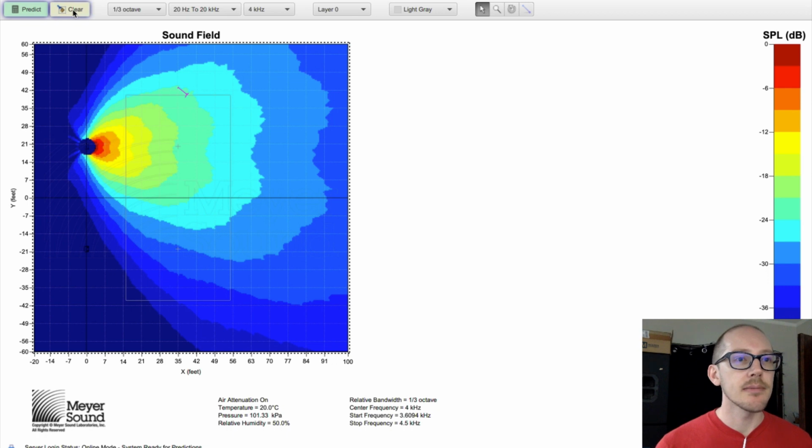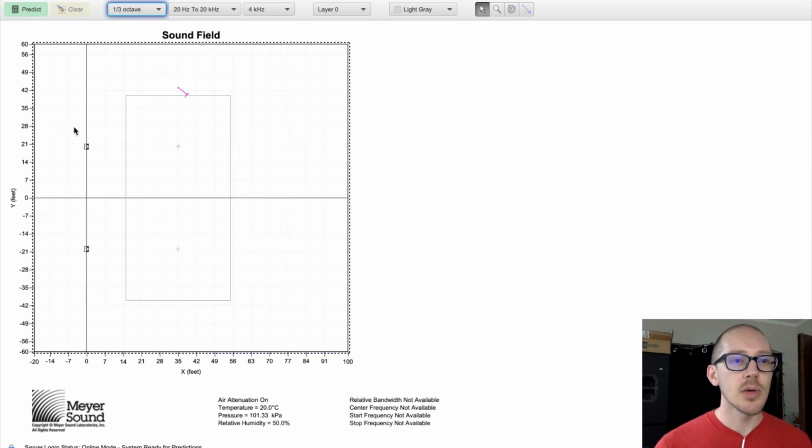But pretty good. Okay, so now in terms of placement, I have a pretty simple method for this, which I'm pretty sure I just got out of Bob McCarthy's book years ago, which is that you want to place at the center of the audience plane. The funny thing about that is that we often want to be in the same position as projection.